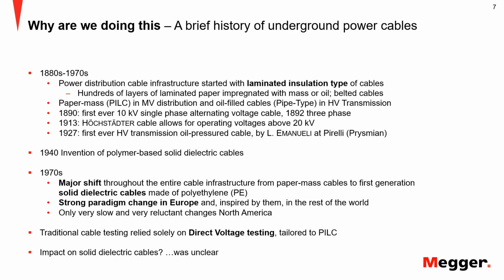So when the third generation of PE cable was introduced to the marketplace, it fixed a central issue of these PE cables, and that was the water treeing. So anything that is put into the ground since the late 80s, early 90s is not just regular PE anymore. It's tree retardant PE, or in general, if you want to describe these cables, those are copolymer cables.